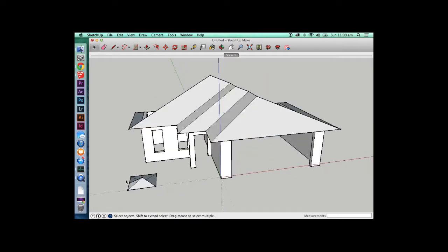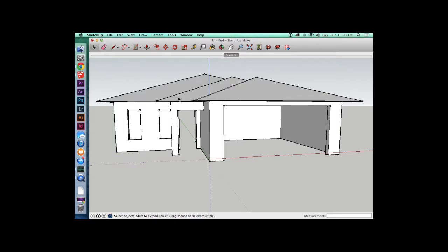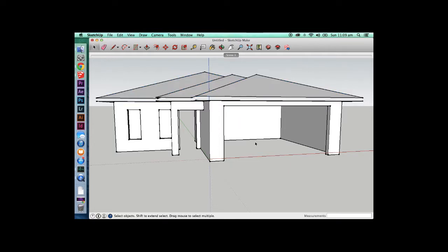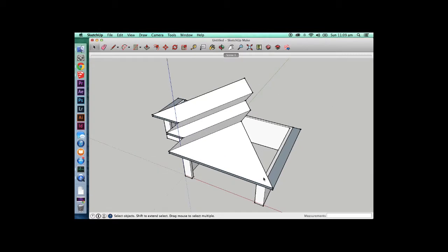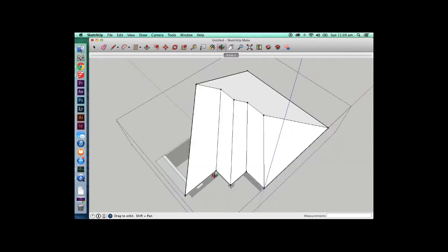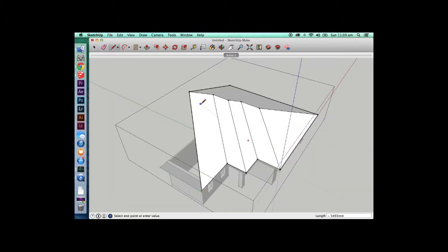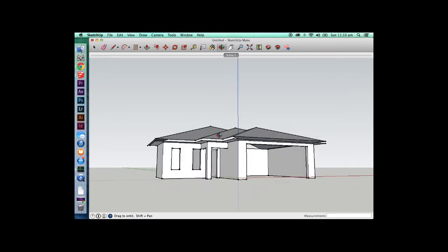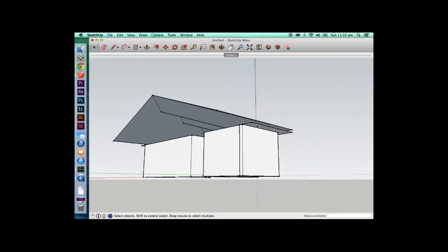So I'm just going to come back and update the scene. Now this is a basic front elevation for an architectural visualization project. I'm just going to move this up 150 millimeters for the gutter that I'll be putting on later. And I'm also going to edit this and add this plane so the shading is correct when I render it out eventually. I won't be dealing with rendering in this section of the tutorial, because that's a whole other tutorial. It's a lot to go through.